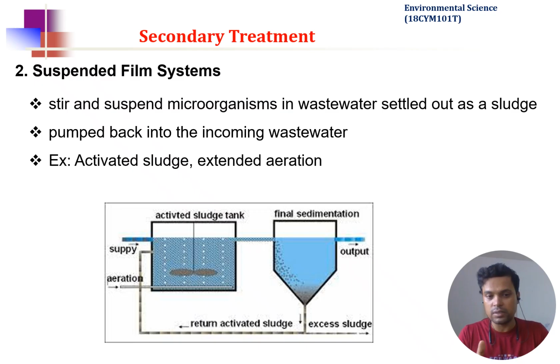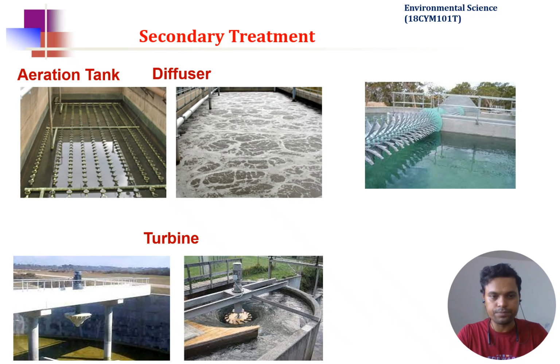Depending on the amount of waste present, you can change the time. You can keep the wastewater with the microorganisms for a few days until the organic material goes down. But in the trickling method, as we saw in the earlier slide, there is a continuous flow. That is the reason why the efficiency is very low in this particular method.